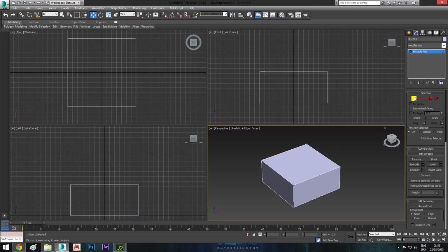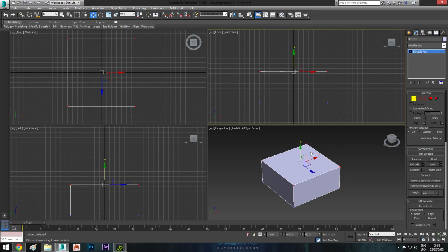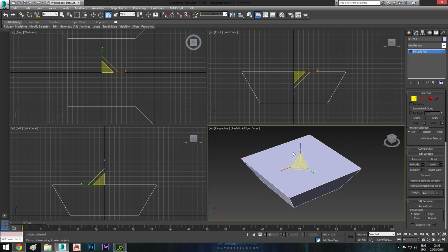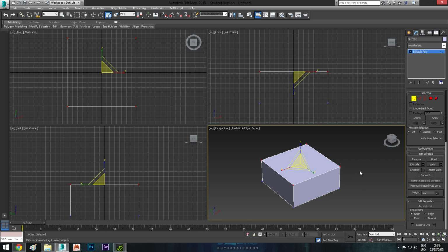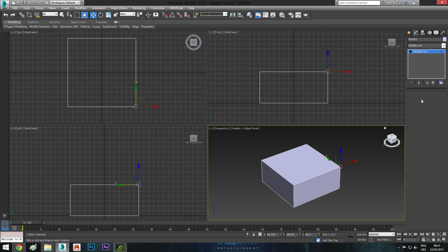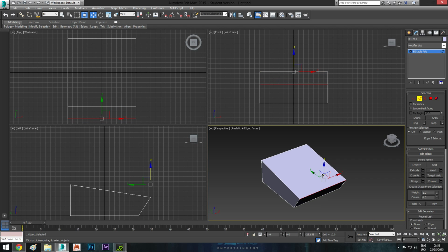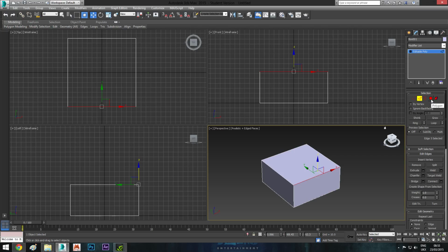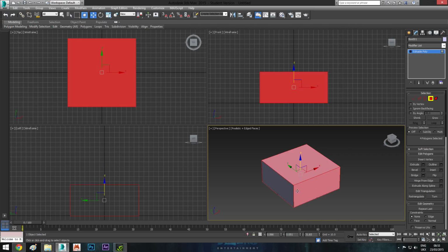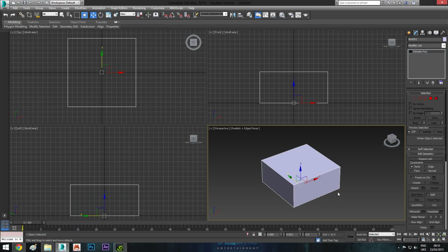Now when you're creating geometry, there's three things to keep in mind. We have vertex. Verts are your corners on each shape, which adjusts the shape. You can select these as multiples or singly, like this. We then have edges, the geometry which you can move and change and alter. Then you have polygons, or faces as they're called, and that's how we select the faces. So in order to create a box, we don't even want to worry about the verts right now, we just want to worry about the polygons.